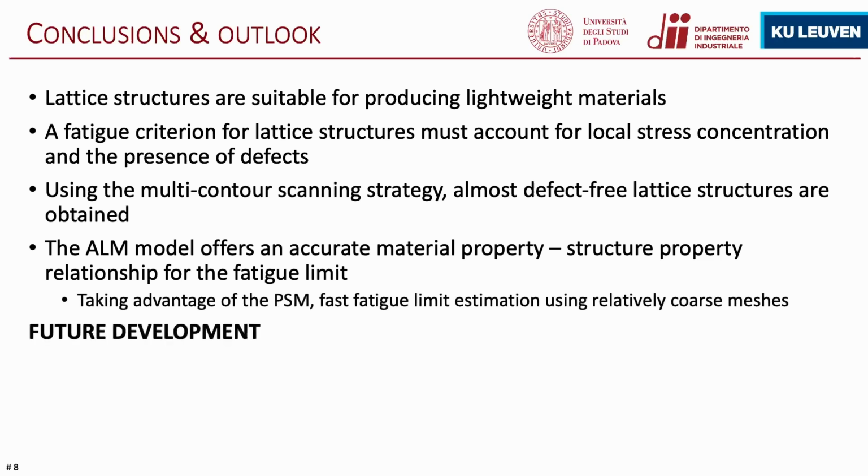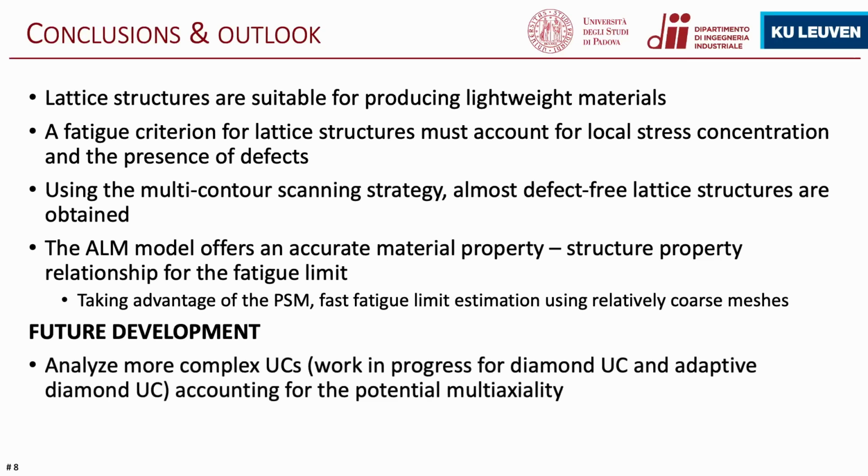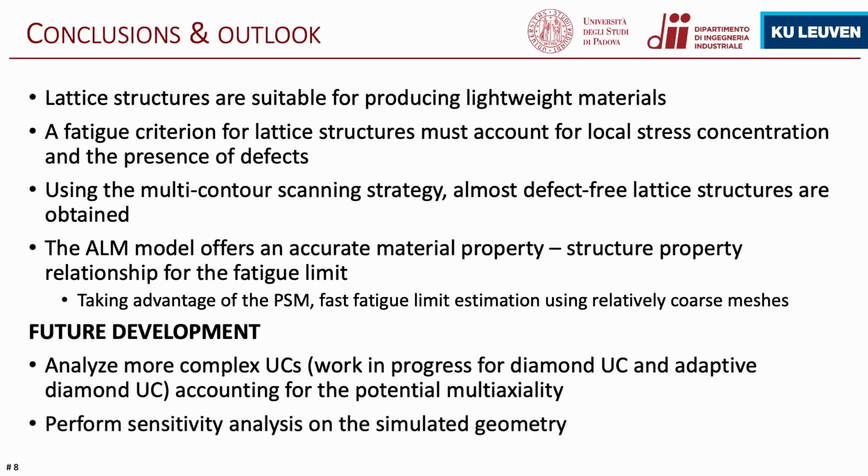Moving on to the future developments, I'm already testing more complex unit cells than the BCC I've shown you today, in particular the diamond and the diamond adaptive that was developed at TU Leuven. And for these kinds of unit cells, I will have to take into account the potential presence of multiaxiality, and I will have to perform a more detailed analysis of the sensitivity of the result based on the simulated geometry.